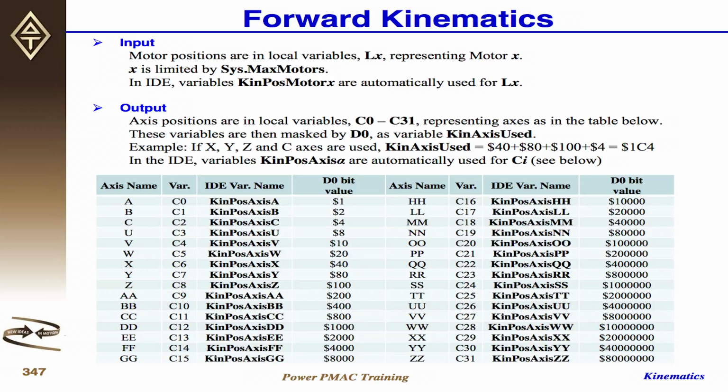That 0 position doesn't really mean that's the 0 encoder counts. There might be some offset, or depending on how you actually home the motor, there might be a different 0 position that's defined in the mechanism in your robot arm. So you have to make sure that already happened and the motor is homed, so I know that the calculation through the forward kinematics will be correct. Okay, that's the first thing you want to check.